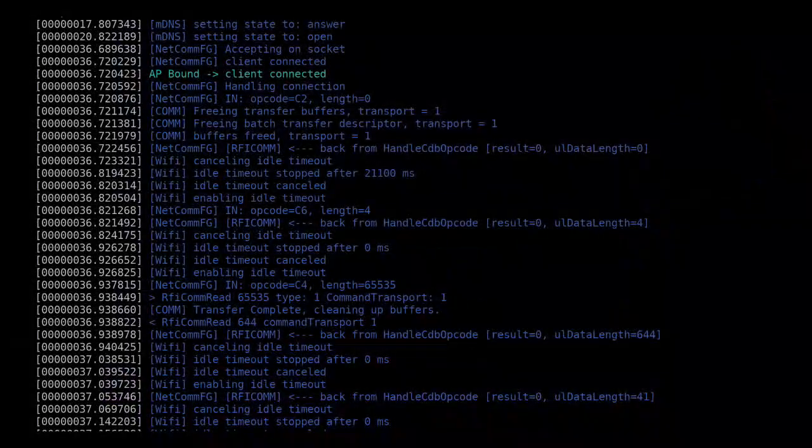So we can unlock the camera over Wi-Fi or USB by sending that correct hash, the secret message that it expects. We don't need to disassemble the device. We don't need to solder anything. I can just have a device with Wi-Fi on it send that unlock code, and suddenly the device is much more usable. So I implemented a remote shell over Wi-Fi basically.